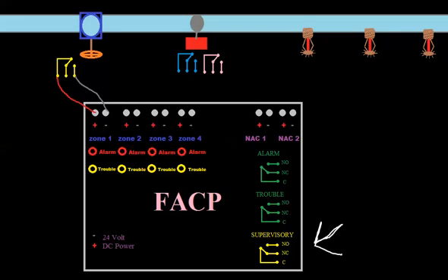And our panel still needs a resistor because we still need to know if something happens to the circuit. So now we draw a resistor. And again, that's the symbol for the resistor. So the current's just flowing through the resistor. If you started to close this valve, at some point this would change states and short out. But since we've already programmed this zone as supervisory, it's not going to cause an alarm. It's going to cause a supervisory, and this relay would change states.